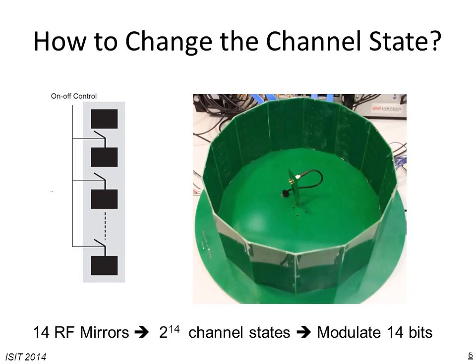the channel state. The way this can work is that the transmitter at the beginning will go through the channel states one after the other and index them from 0 to 2 to the power of k minus 1. The receiver measures them and knows that they are happening in this particular consecutive order, and will know what constellation configuration at the receiver corresponds to which bit pattern at the transmitter.